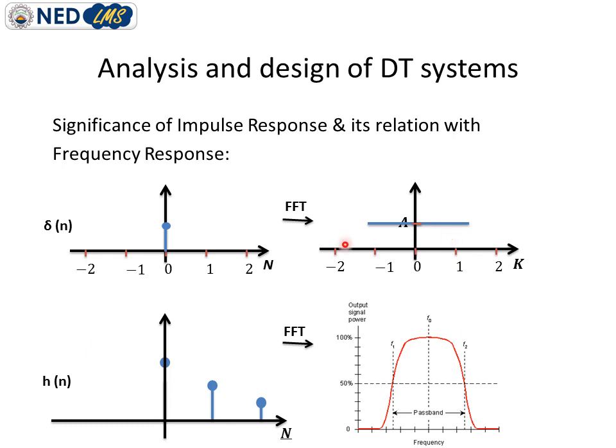All the possible range of frequencies is applied to the system just by applying a single impulse at its input, because this impulse function appears to be all possible range of frequencies in the frequency domain. So this means in the frequency domain we are applying all possible range of frequency, which is very similar to the procedure we were doing in the first method manually.